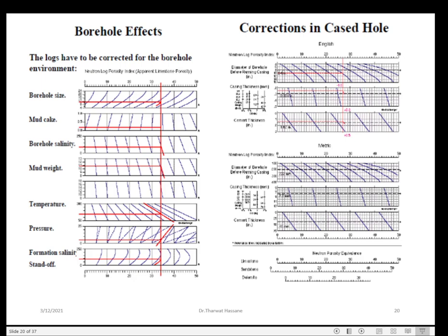So please, guys, when you do this, ask the surface company to do the temperature correction. I was actually an operator company before, and unfortunately, when I looked at the logs, I found it doesn't do the correction for temperature. So I asked the client to ask the surface company to do it from now on. Before I joined the company, I found a lot of logs that were not corrected. So please, this is very important to do, because I will show an example of the effect.